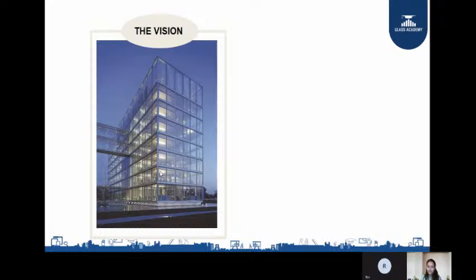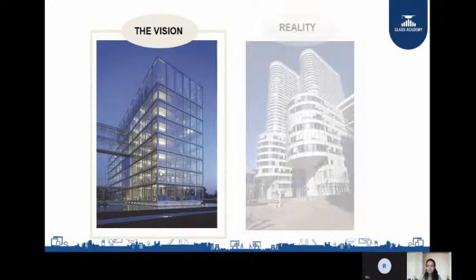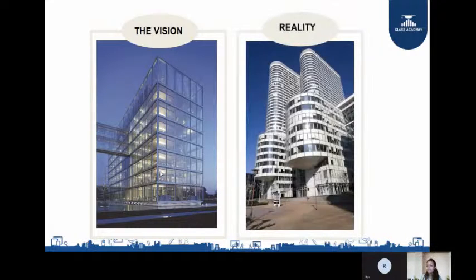Ultimately, this system compartmentalizes a building into sections to help contain and slow the spread of fire and smoke. This is a main objective of ours, right? We need to contain the fire in one particular location so that people can evacuate the building, right? But we need to ensure that the building and everyone inside will be completely protected, and it needs to have both passive and active fire protection systems.